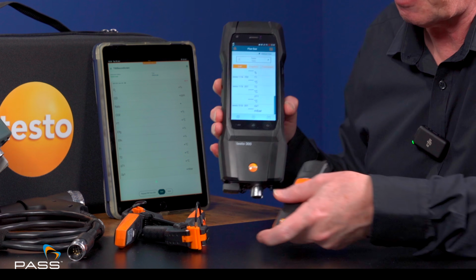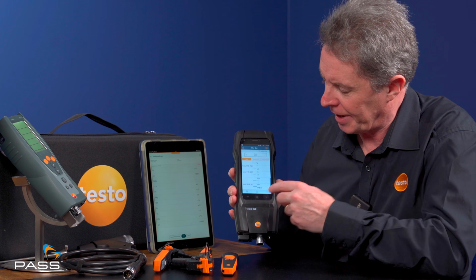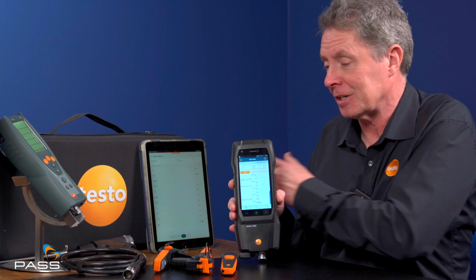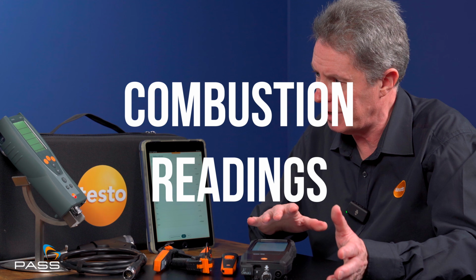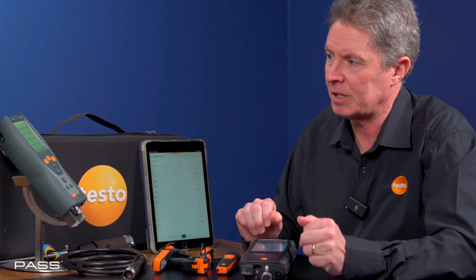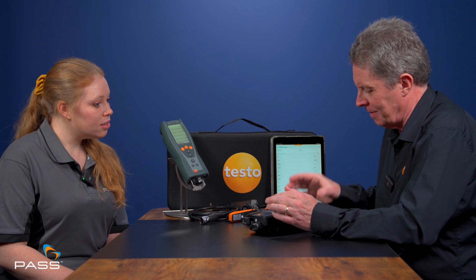And I've also got the Testo 510i, which is our digital manometer for gas pressure. So what we've now got the capability of is getting these smart probes, rather than having to connect to the app, to talk to the 300. And then the 300 is talking to the app. What this really means for an engineer is you can have your combustion readings, your flow and return temperature, and your gas pressure from maybe the gas valve all on the screen at one time. So it's a really powerful measurement system. If we look at the 327, you'd have to do that across multiple tests. This is all these measurements on screen at the same time.